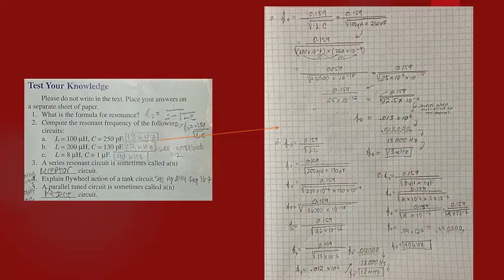The way this works, I'm going to help explain this, I'm going to include a graphic. But basically, you have a switch in line with a parallel capacitor and an inductor. They're both in parallel, and there is a switch in between them also, so there are two switches in this circuit. When you first close the switch, in this case switch 1, which is the one closest to the power source, and open up switch 2, you charge your capacitor.